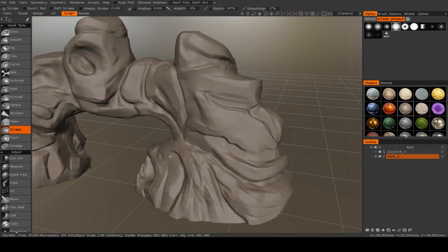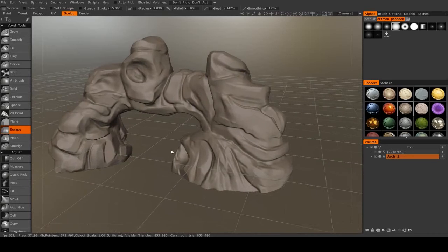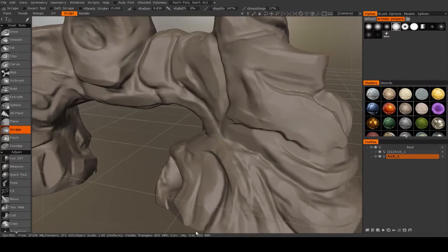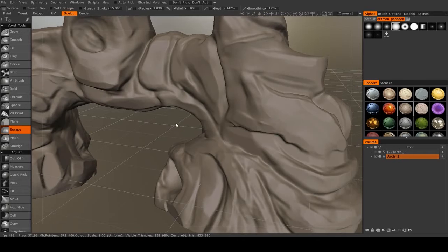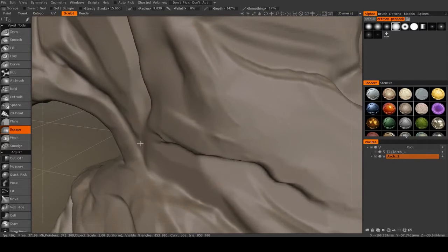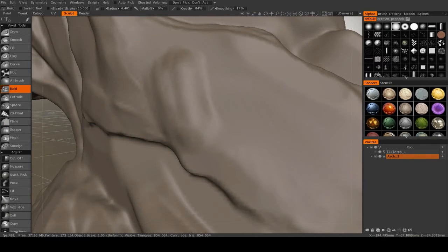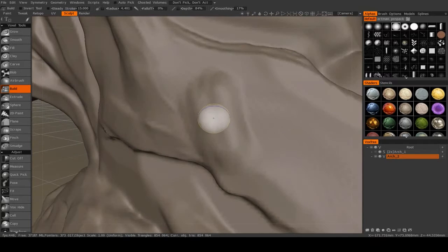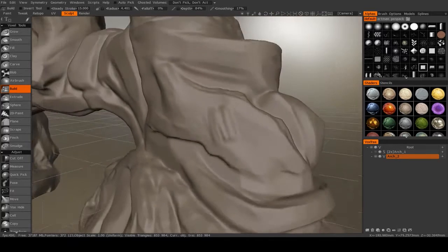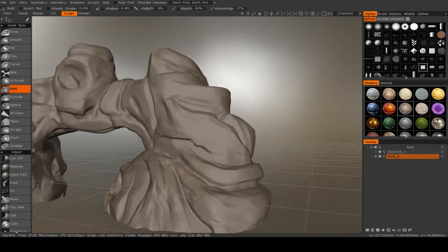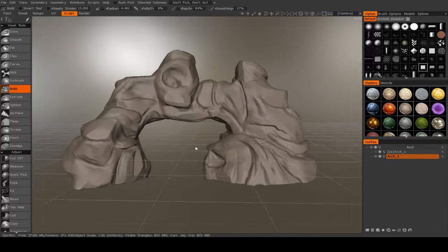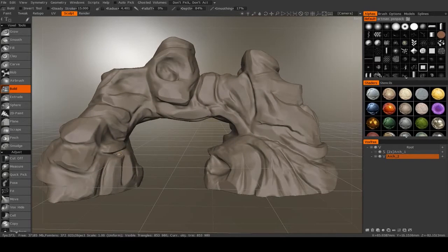on some smaller shapes. Now, with the voxel resolution that I've been using, it's resulted with me having about 853,000 triangles. And if we look real close, if I were to go with my build brush and start to build, it's going to be difficult for me to create nice looking forms that are smaller than the ones I've already got. We just really don't have the polygonal density for those to look very nice. So for this step, we're going to increase the resolution.